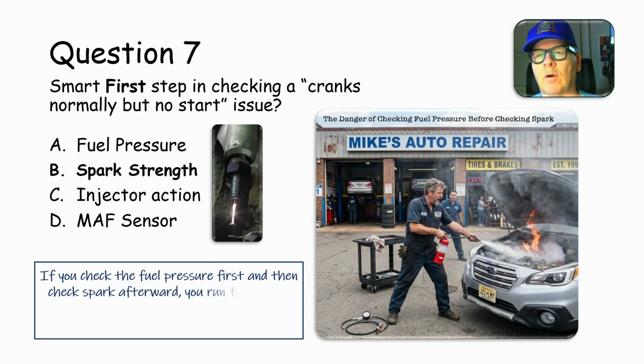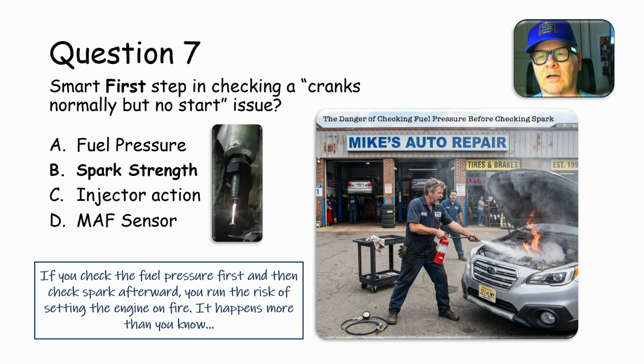All right, so the smart first step is to check spark strength. Don't check fuel pressure and then check spark. That's just a bad idea. I had told you guys one time about this, and I did not make the mistake of checking fuel pressure and then spark strength. I had already checked the spark, and I put it all back in on this Taurus I was working on.